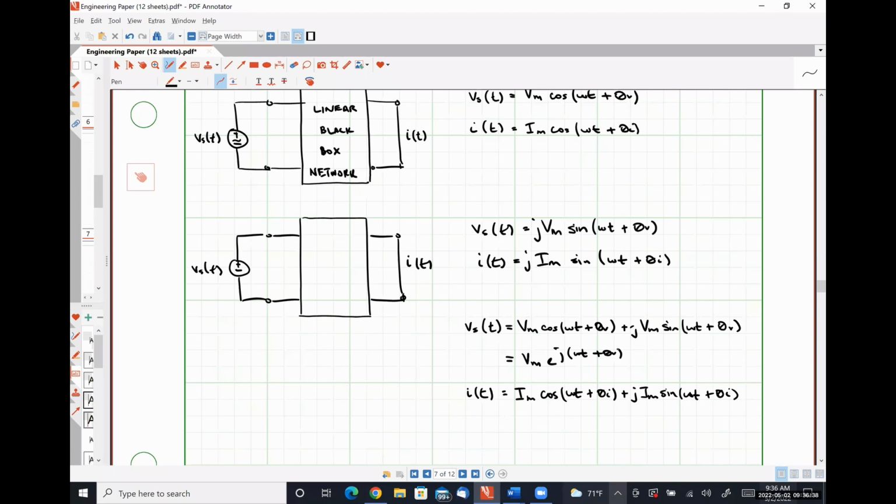So what this means is that we can analyze a circuit using a complex number to represent our real time domain input signal, get a complex output to our system, and know that the real output is just the real part of our complex representation.